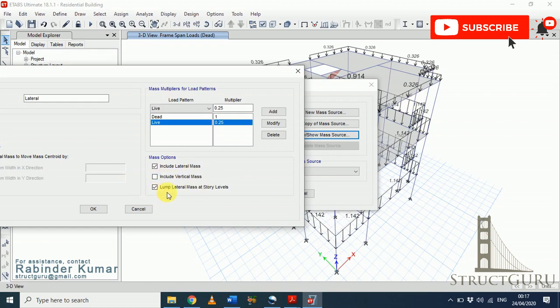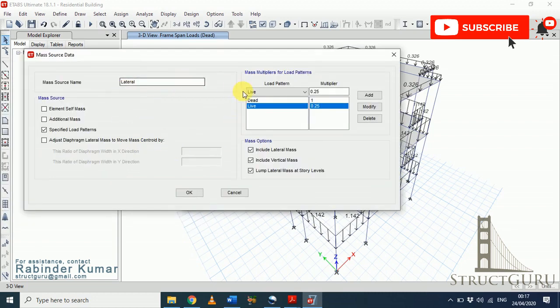And the third is lump lateral mass at story levels. Basically that means all the self weight in the mass source is considered to be accumulated at the story level, so you have to check this option. If you want to check all 3, it's okay, it's not a big deal. This way we have to define the mass source data in our model. So once we are done, click OK.